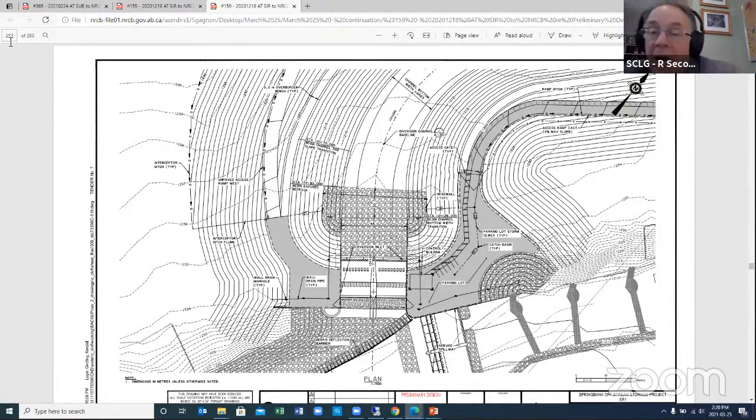If the water hits the access bridge, how have the impacts of friction been included in the diversion inlet rating curve? Sure. As I said, we perform the appropriate calculations to look at the effects of whether it's weir flow or orifice flow, and we performed hydraulic modeling that incorporates those physical processes to confirm those effects.